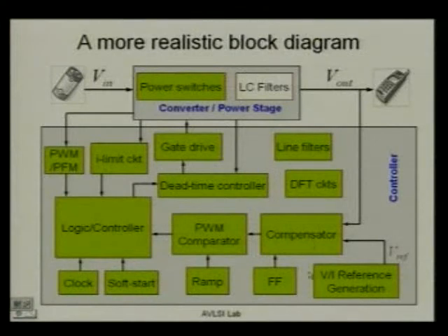But getting a reference voltage is not that straightforward. You might have gone through your band gap reference course in your analog, or I'm not sure if you have, but just keep in mind that there is something called reference generator circuit, which is a very simple circuit. If you have already gone through it, then okay, you will understand. If not, they will discuss it in the coming analog lectures. Reference generator, so there will be something for generating the reference. Why we call it reference? Because it has to be maintained constant. It won't vary with temperature, it won't vary with your chip input voltage, it won't vary with anything. So that's why it's reference.